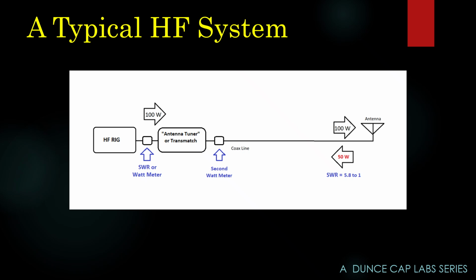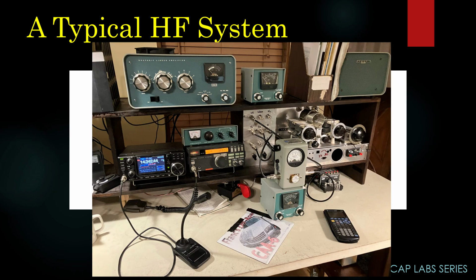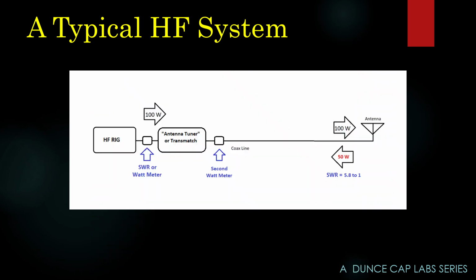Let's go back to this system. Let's put the antenna tuner back in line. All right, here we go again. Radio. Its output goes here. It loops, goes to the meter, comes back, goes to this jack you can't see, which goes to the tuner, comes out of the tuner, goes through the watt meter, out to the antenna. So we have built this. Let's see what we have.